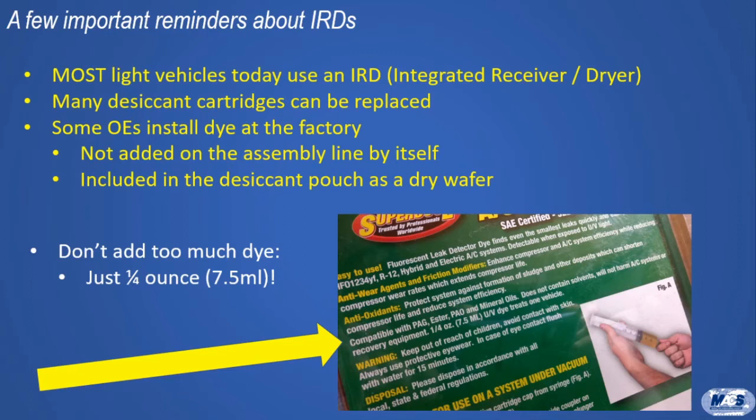Most of us add dye in the form of a liquid, and part of that liquid is usually a universal refrigerant oil. Too much oil can be nearly as detrimental as not enough oil. And refrigerant oils, refrigerants, and coolants are constantly changing.